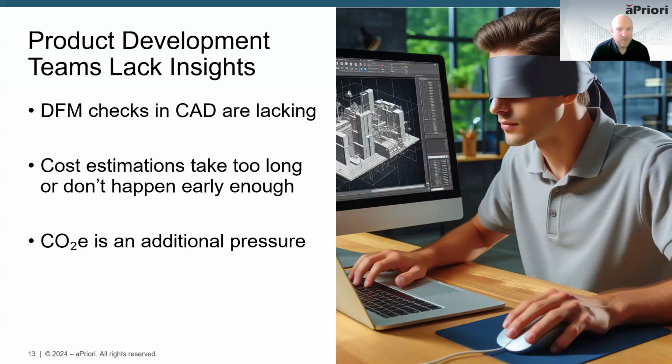DFM checks in 3D CAD are quite limiting as well. You need a lot of data to use them effectively and to interpret the results. So it can make the decision making very, very complex. And without the cost estimations up front in the design phase, again, you're lacking some of those insights.